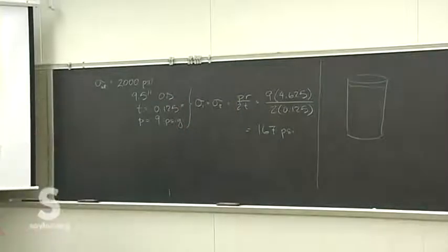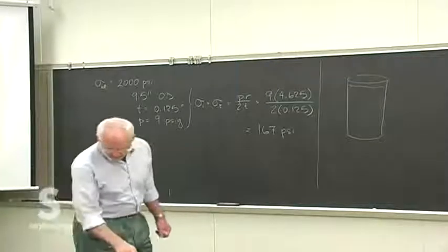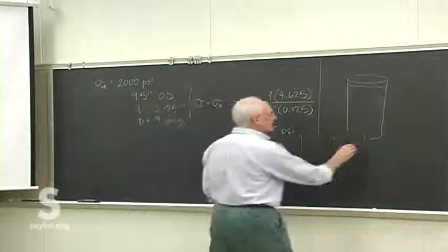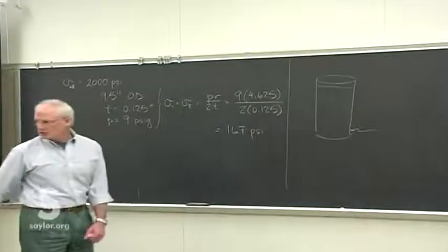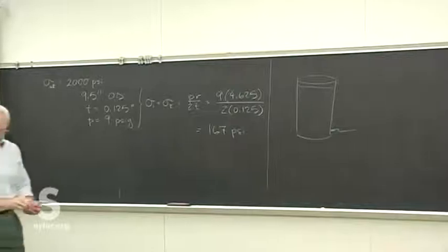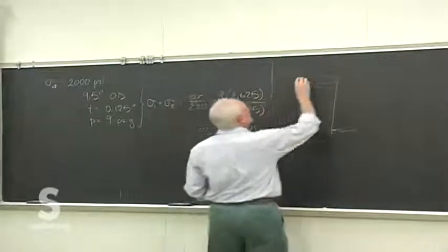So you're not going to need a spherical end cap on the top of this because that's not significantly under pressure. It's the bottom down here that's going to see the greater pressure since the pressure varies with depth in the tank.